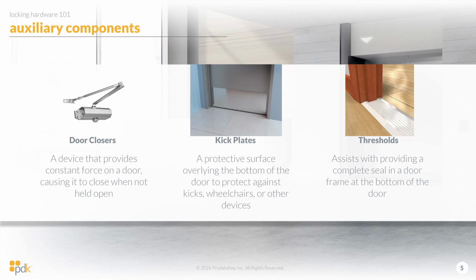Kick plates will prevent the bottom from getting all scuffed up and damaged. Those are typically done on high traffic doors, bathrooms, places like that. And then thresholds will help mostly with weatherproofing. Prevent water ingress in places where you don't want it, perhaps prevent smoke from seeping underneath the door, things like that.